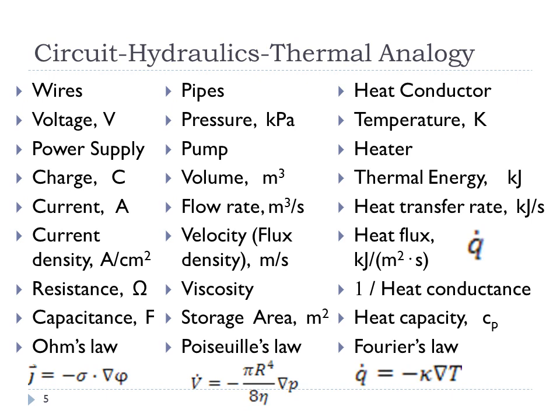And here, the equivalent to resistance is the viscosity of the fluid in the pipe, and the storage, like the capacitance, is meters squared. Like when you're doing circuits, you can always draw a capacitor. Well, you can do the same thing with pipes, where you have tanks, right? So a tank is effectively like a capacitor in this analogy. And what matters is the storage. The equivalent of capacitance is the storage area.